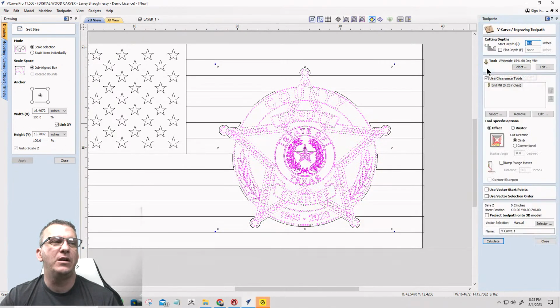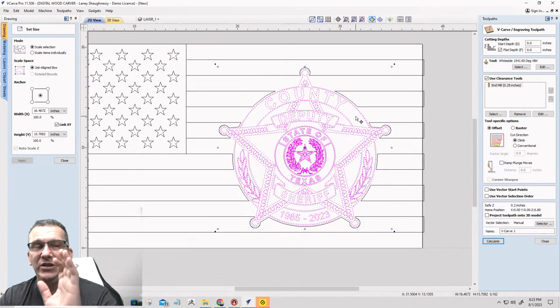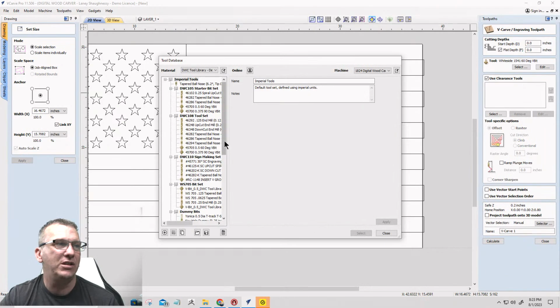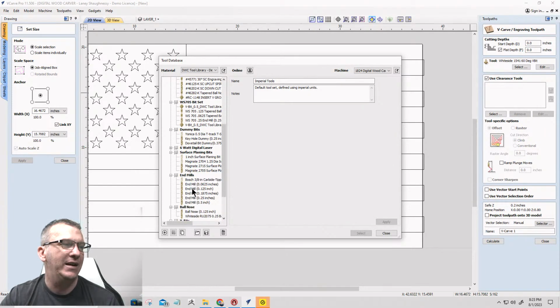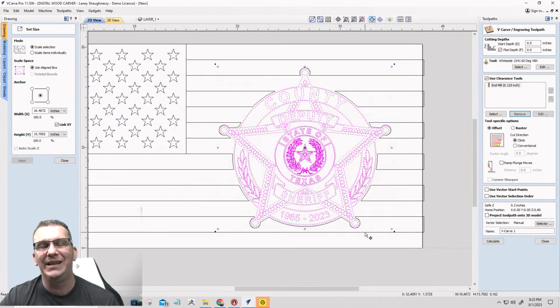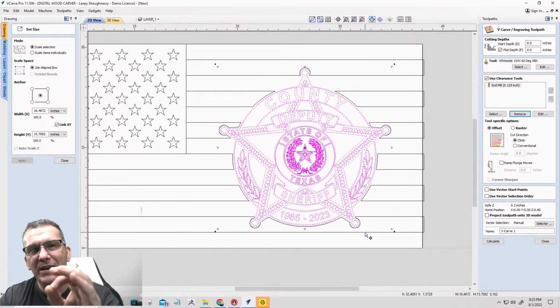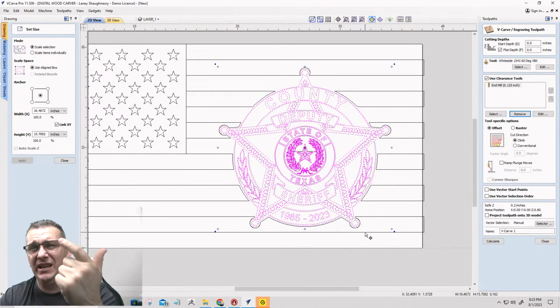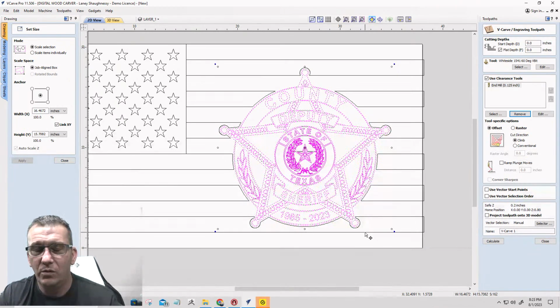So we're going to go VCarve toolpath. On this one, I will set a flat depth because there's a big old wide gap. I don't know how deep it's going to carve, so I am going to set a flat depth, and a 1/4 inch bit isn't going to cut it. I'll use an 1/8 inch to help out with the flat areas. So your bit selection, your end mill, your clearance tool, is going to be based on how big of an area it fits, you know, 1/8 inch, 1/16 inch, 1/4 inch, 1/2 inch, whatever.